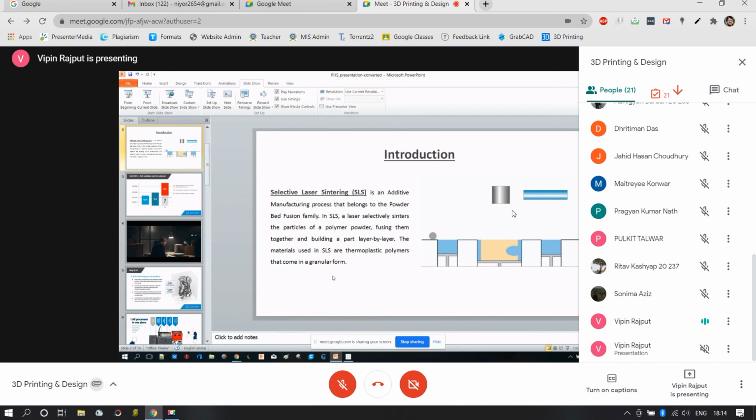See, basically, the VAT polymerization process involves two to three or even more subcategories. Projector based polymerization is one of the techniques. Then laser based is one of the techniques. LED based is also available in the market, as well as LCD based. But in case of LCDs, the pixel resolution, nowadays you can see 8K, 4K, very high resolution pixels are available over the screen. Thus, if you use LCD screens, it will offer you much more precise and much more detailed objects compared to the other two.